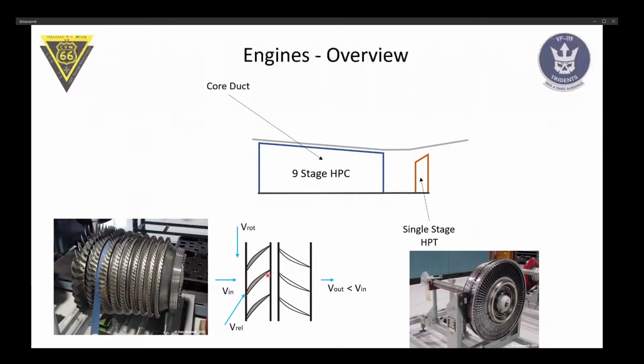And they work like a wing, more or less. They create lift, and first of all they create pressure, and then they rotate the whole airflow. So if you look down the channel, these rotors swirl the air, and what happens then? The stator blades take the swirl out. The air comes in at this angle into the stator, and it will straighten out the flow, which will create additional pressure, because you don't want swirl flow, you want straight flow, which gives as much pressure as possible, and this is what the stators are for. They straighten out the flow.